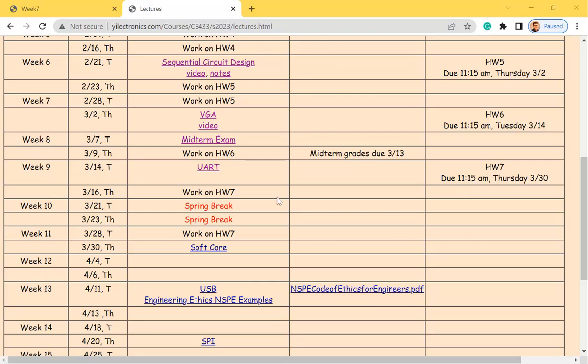So how can we design the experiment to verify the logic of the UART? Instead of using a microcontroller which has RX and TX, it's going to be the FPGA board which has RX and TX available. You can imagine that's your Basys3 board, which has RX and TX on the board. How do you verify the logic? Yes, we will simulate it, definitely. How to verify in the real world with any resource we have in the lab?